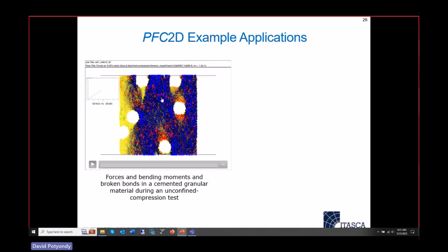There's also cement in here, what we typically call a bond. What we're going to find out is when you squeeze a granular system that's bonded, you compress it this way, and you're going to cause tension in this direction. So black is compression in the cement. Red is tension in the cement. This induced tension is the thing that breaks the bonds.